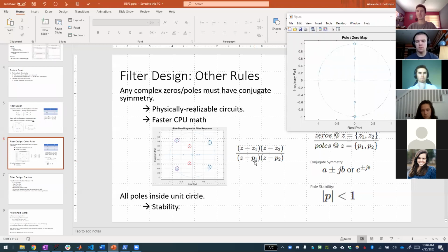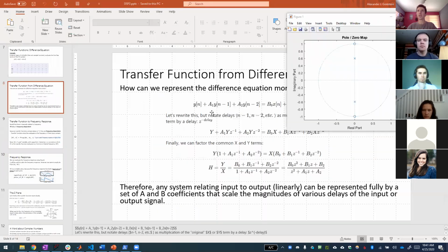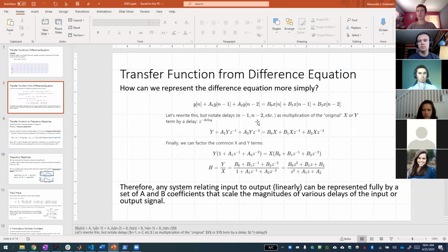But to get back to the difference equation, you had to multiply these to the other side, so as a consequence, these A terms cannot be bigger than 1. As a rule of thumb, if you're setting A's and B's, these A terms can't produce gain on whatever it's outputting, because then you just end up in this feedback loop, right?